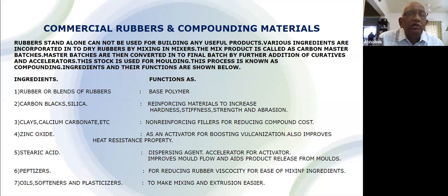Then comes the carbon black or silica. These act as a reinforcing material. As I told you, rubbers alone cannot be used because they don't have that strength. So by adding reinforcing material, rubber will develop hardness, stiffness, strength, and abrasion resistance, which are ultimately responsible for the product to function or perform. Then different types of clays, calcium carbonate, etc. are used, but these are non-reinforcing fillers.